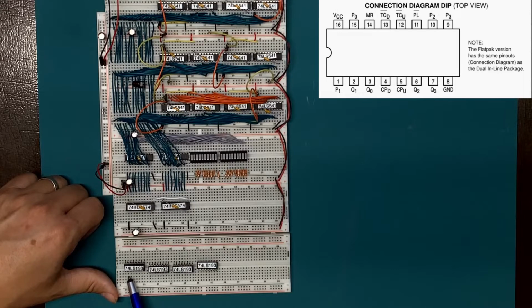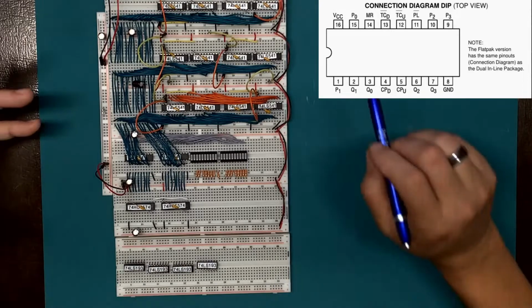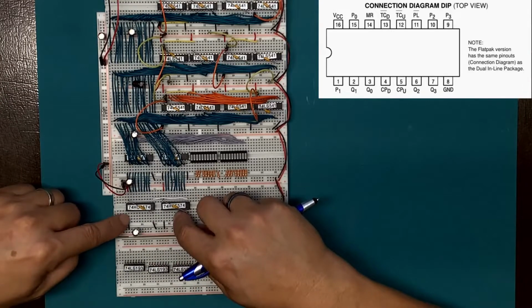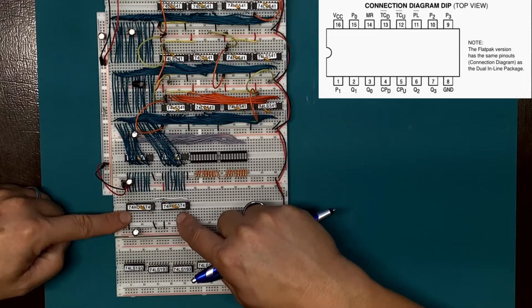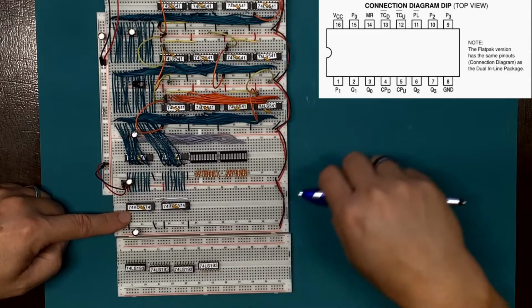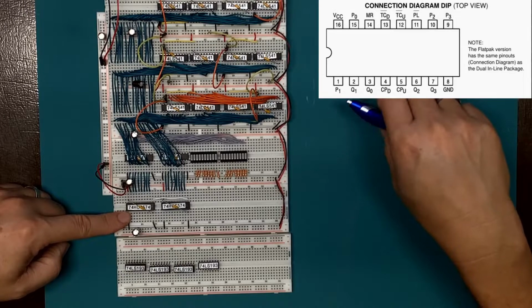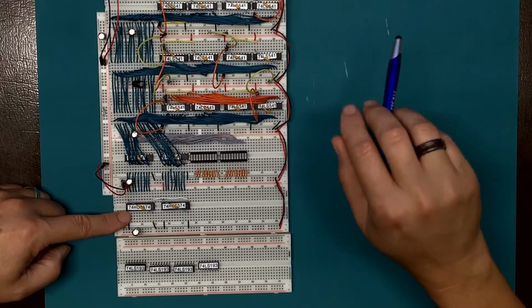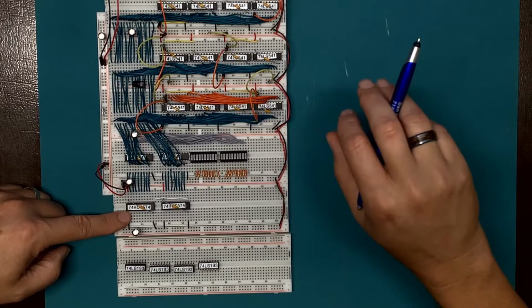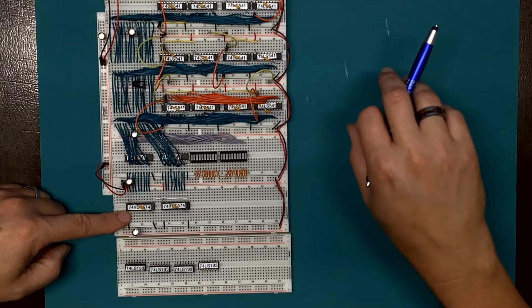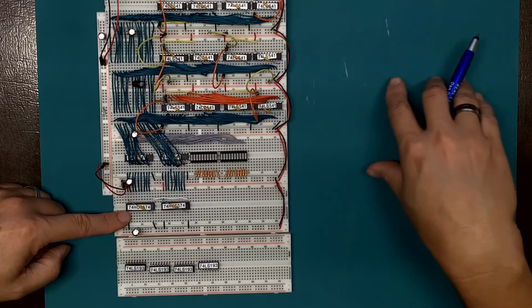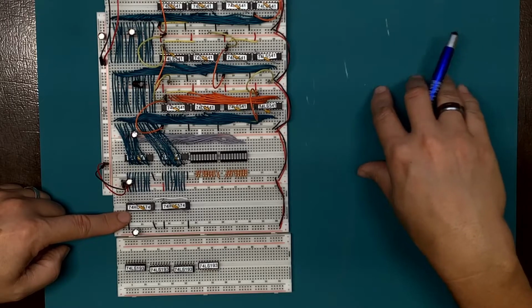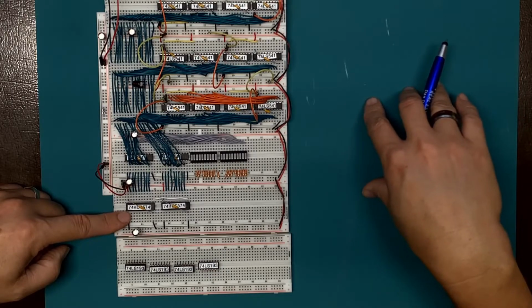So it's 0, 1, 2, 3, which then all need to come up to the inputs into the register up here. And then my loading happens up here. It's not an ideal situation. I did look through some of the other integrated circuits and the pinning associated with those to see if anything got any better. The only one that did was the 169 that I saw. And again, that one doesn't have, I believe, all the functionality that we need.